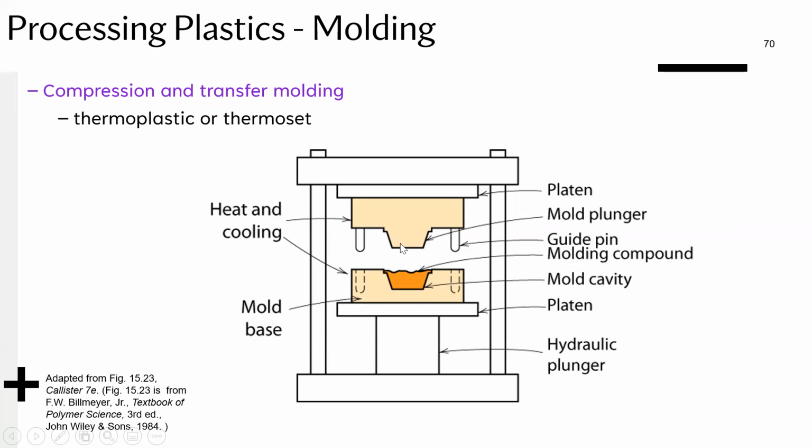So you're going to actually heat it up. Usually these bases and also the mold, both of these pieces are heated up. So you heat up the material until it's reached the temperature that you want. Then you compress the extruded top piece onto the bottom piece, and that forces the material into the certain shape of the cavity. You cool it down and you remove the part. Now, all this will be a lot clearer when we actually do the next slide.